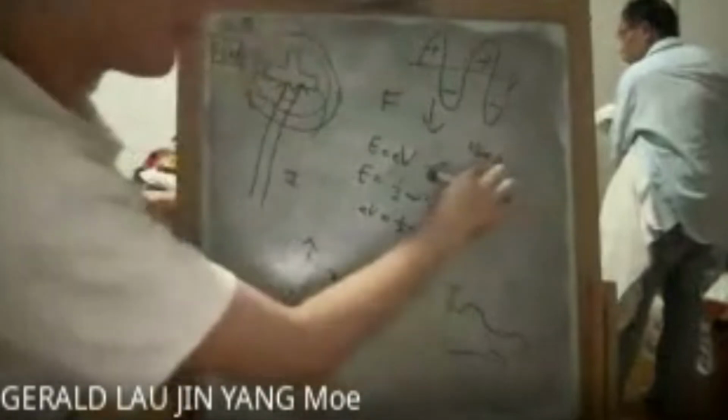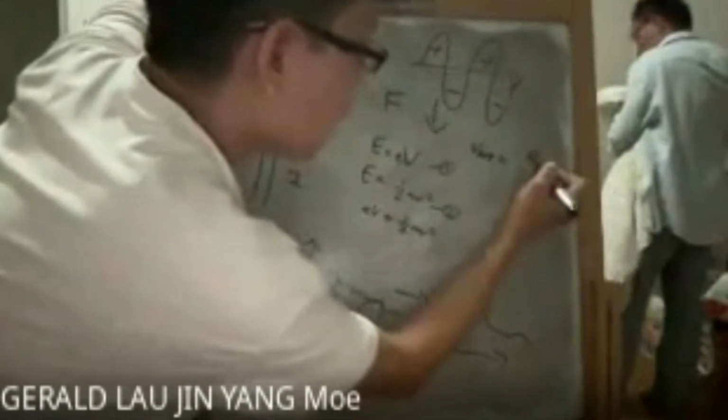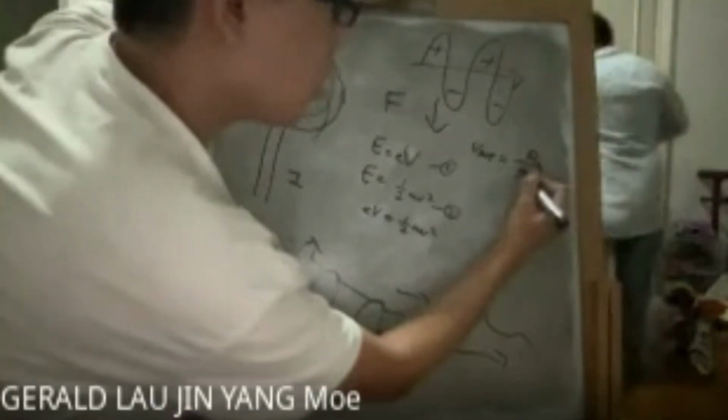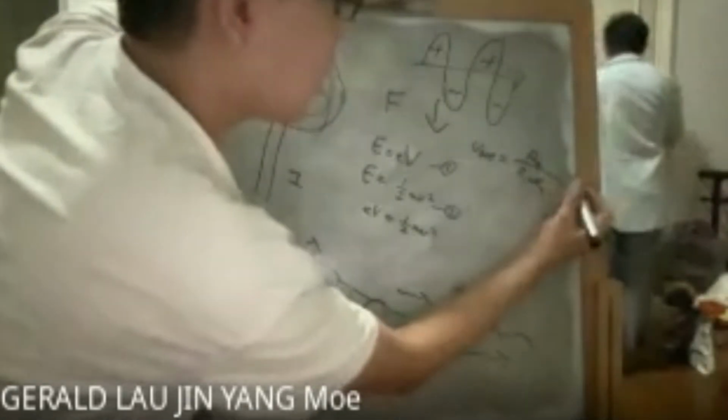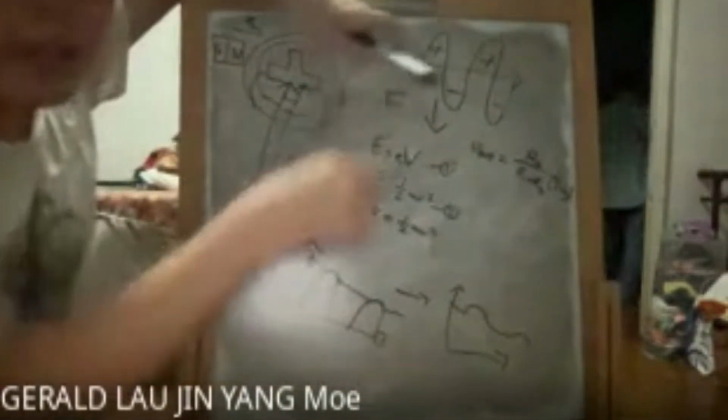Okay, that means your V out, okay, you know your V out is this small specific region. So you take the R2. The R2 is the specific region over the total resistance R1 plus R2 times the V in, the total voltage. Okay, this is the formula.